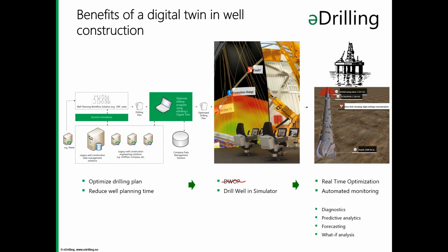And for an optimal well construction process, take the same well, the digital twin of your well, and use it in real-time optimization and automated monitoring of the actual operation. In real-time operation, it enables you to do forward simulation and what-if simulations to detect mismatch and give input to change the drilling plan, for example, to avoid problems or to change parameters for optimal drilling, or in other words, drill the perfect well.